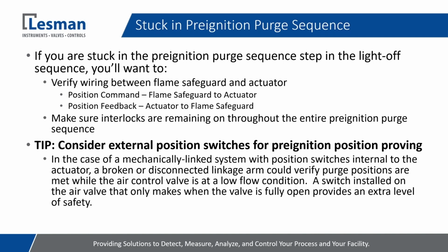So at any point during that, if you lose communication and you're not getting the position feedback, the Honeywell will wait, and the FireEye will wait, for a certain amount of time before faulting out. It'll say, okay, I haven't seen my high fire switch make after 4 or 5 minutes, and then it'll cause a fault or a lockout. So if you see that it's indefinitely waiting, you definitely want to check and make sure that you're getting that handshaking properly.